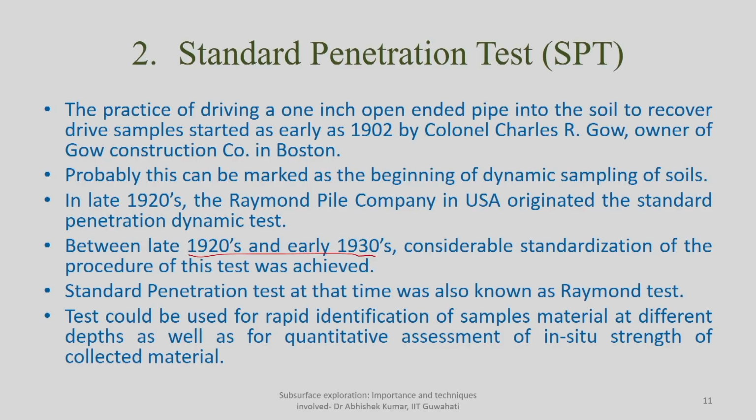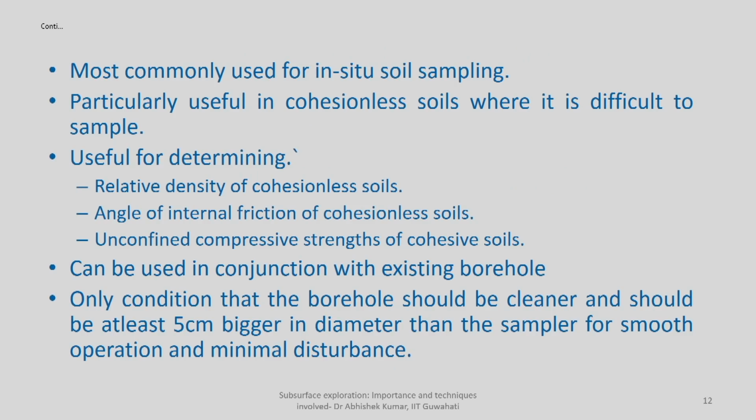So it can be used for rapid identification of sample material at different depths, as well as for quantitative assessment. You will be able to get some quantitative assessment of the in situ shear strength of the material. The vane shear test was for fully saturated soft clays; this also gives you some indication about the shear strength property of the material. It is most commonly used for in situ soil sampling, because so far, whatever tests we have discussed, whether auger boring or wash boring, other than rock sampling, which is particularly used for fractured rock, weathered rock, intact rock, the SPT test we cannot use there. But this is the most commonly used test where you are collecting the soil sample.